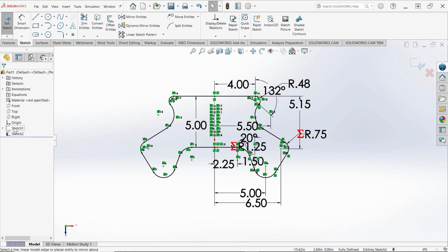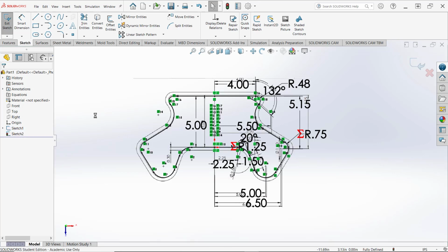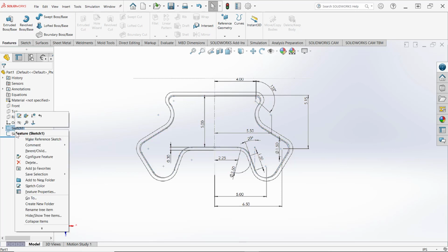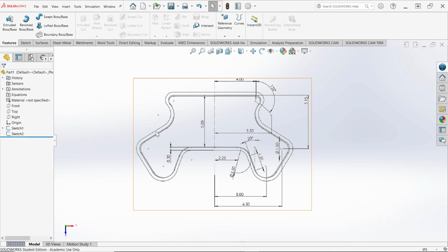Now on our original sketch, there's a thickness here of 0.3 towards the outside, and I took off the thickness, but I think it was 0.2 from top to bottom. And so I'll finish sketch, and I will hide my sketch 1, and actually let's just leave the image on for a minute. Let's highlight sketch number 2, so it's highlighted.